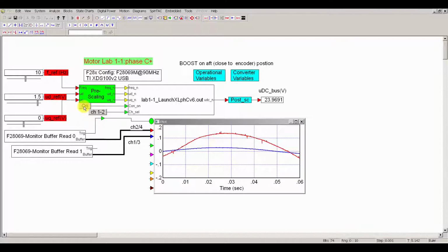And lo and behold, you can now feel the effect. We are seeing the voltage on this one. If I increase the frequency, it will start to spin faster. At 20 Hertz, as it is now, it means 300 RPM in this case. If you hold it, you'll see that you can actually stop it. It's not very robust. The red is the current, and blue is the actual voltage.